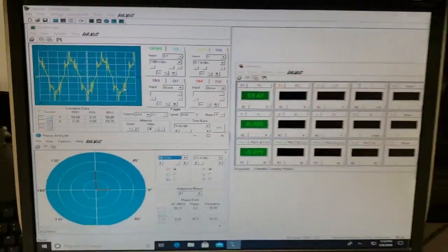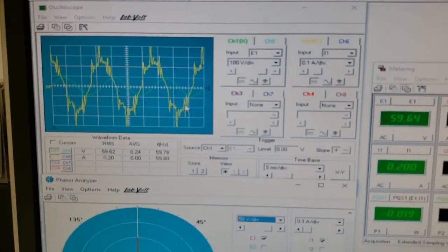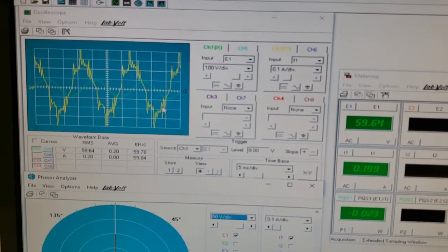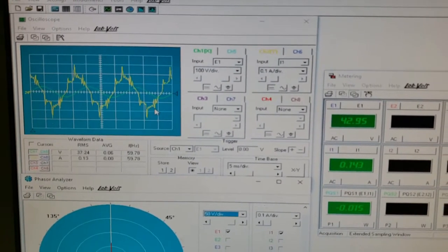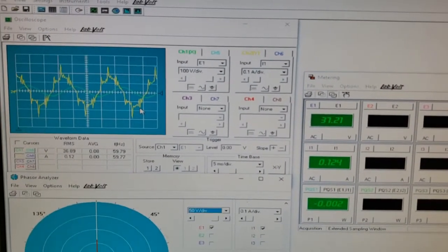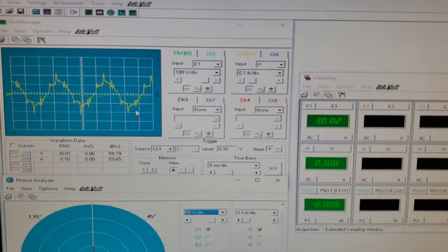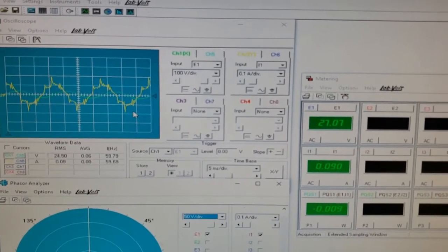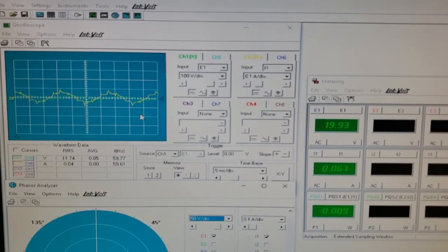I'm going to hypothesize real quick, and I haven't tested this: if I lower the voltage, the nonlinearity should go down to the extent that we maybe can see a purely sinusoidal waveform. So I'm going to test that out real quick. Let it update slowly. You can see the voltage going down on the right there. Wow, no, it doesn't seem like it's going away. Not really. The same proportion of harmonics is still there, very clearly. Let me go down to about 10 volts and see if that kills any harmonics.